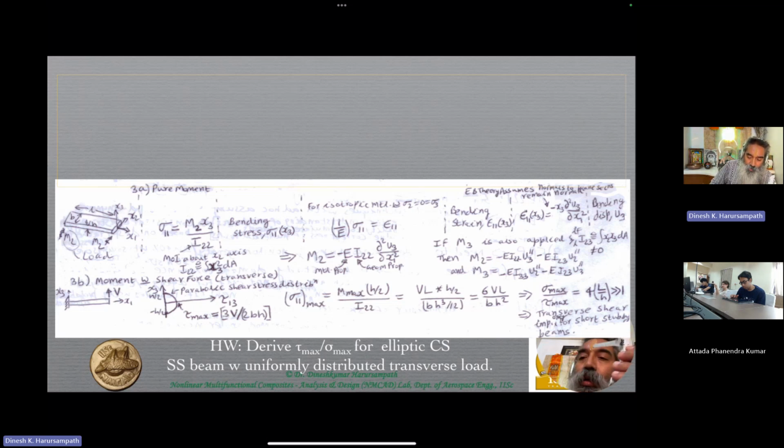Then, what we call the mean aerodynamic chord, you would see that you no longer can use a beam kind of a model for modeling the wings over there. You will have to make sure that you use an appropriate plate or shell kind of a model instead, if you want to get reasonably accurate results.